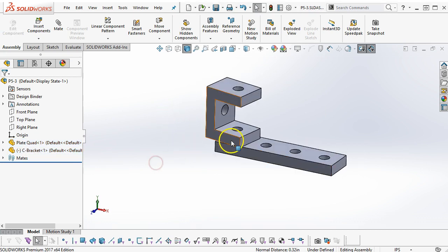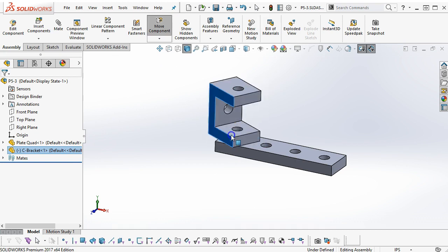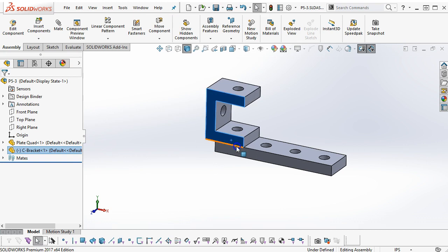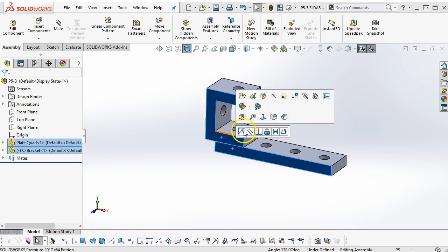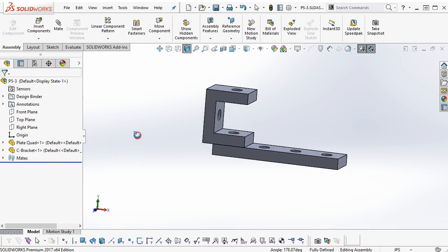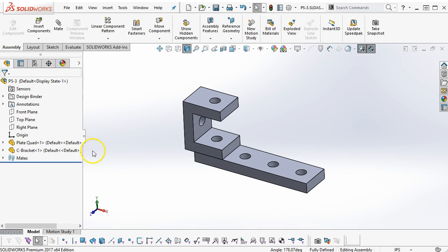And then we can go to coincident. So select, Control Select the two planar faces. Now we have rotation, so we're gradually getting through the six degrees of freedom. And when we reduce this to coincident or parallel, then that will give us a static part.